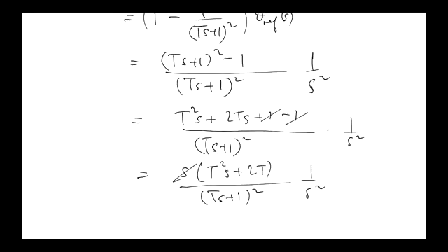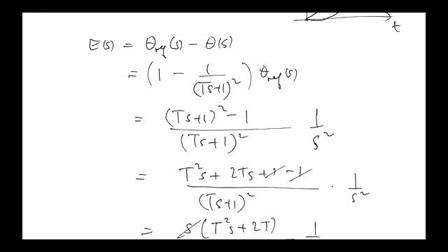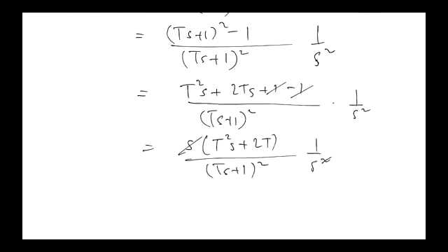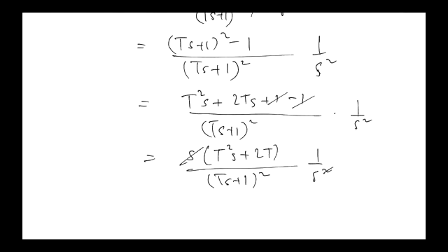All right, so this goes with one of these. And we see that the error signal, which is the thing we started off with up here, is like the step response, that's like a step input, to a stable transfer function. All right? So you would expect the error to reach a constant value, right? Because the step input to a stable transfer function eventually causes the output to go to a constant value.